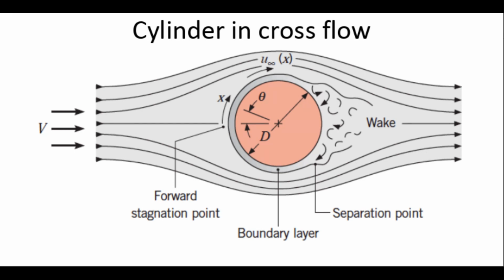And so you're going to have a boundary layer. This boundary layer at the beginning sticks pretty well. And then it gets thicker and thicker until it reaches something called the separation point. It's related to the pressure gradients. But the bottom line is, at some point, this boundary layer breaks and turns into this turbulent wake. This is what gives most of the drag in your car, this wake. That's why very often sports cars have this kind of fastback, so you minimize this wake.